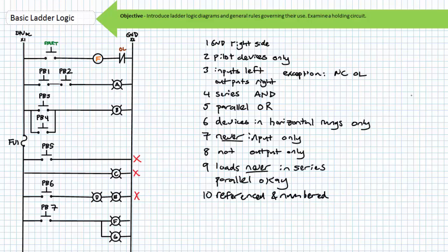Ladder logic diagrams must be properly documented, referenced, and feature properly numbered rungs and wires and fully identified components, terminals, and contacts. We'll discuss documentation, rung numbering, wire numbering, component identification, and referencing in a later lecture. Finally, and this may sound like nonsense to you right now, but you'll appreciate this advice later. All internal logical loads ordinarily appear in the top half of a ladder logic diagram, and all external output loads appear in the bottom half.